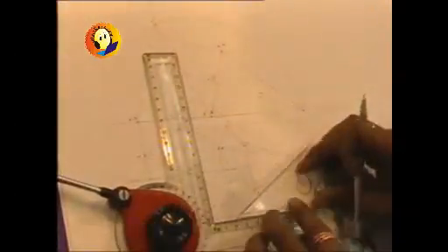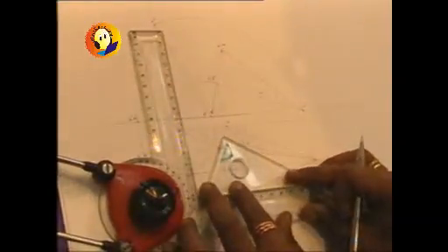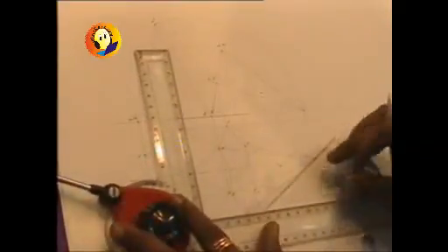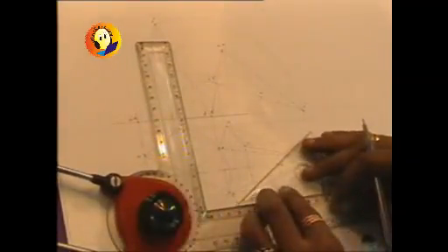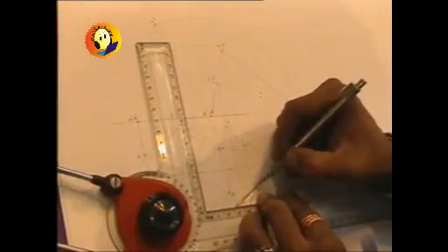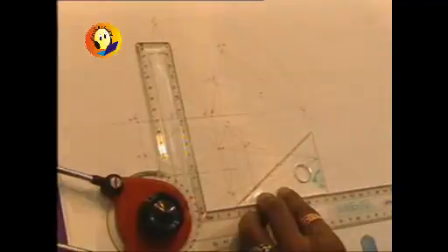And then we are required to draw a cutting plane which makes an angle of 30 degrees. Obviously, I can take the cutting plane in this manner, 30 degrees, or it can be taken in this manner, 30 degrees. Remember, which portion you are removing is very important. We are looking from the base, in this direction, away from the observer, away from the XY line. We are looking towards the XY line. So the portion towards the observer should be removed, and so I am choosing the cutting plane in this manner. So the section plane is passing in this manner, making 30 degrees with VP.